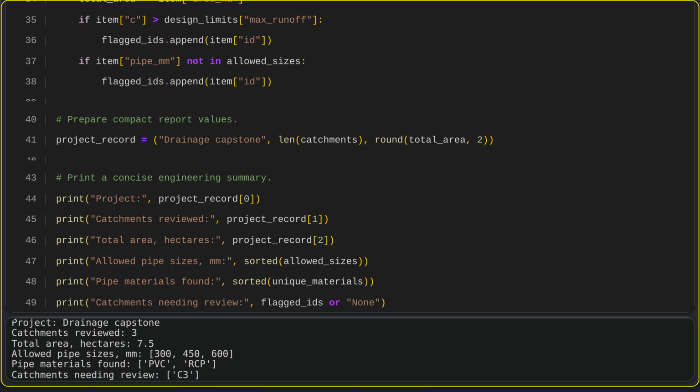Use comments and documentation to explain the reasoning and engineering assumptions behind a script, not to repeat what the code already shows. Clarify choices such as filtering data fragments or rounding quantities, but avoid excessive comments that create confusion. A good test is whether a junior engineer familiar with the project can understand the logic and assumptions without needing much extra explanation.